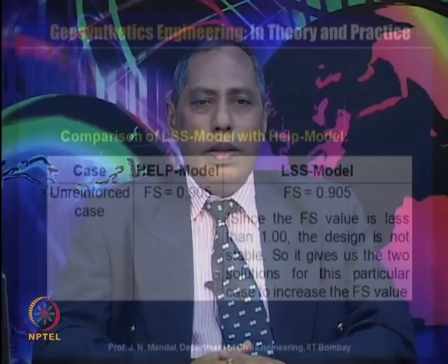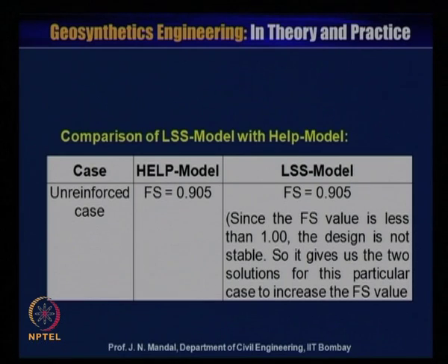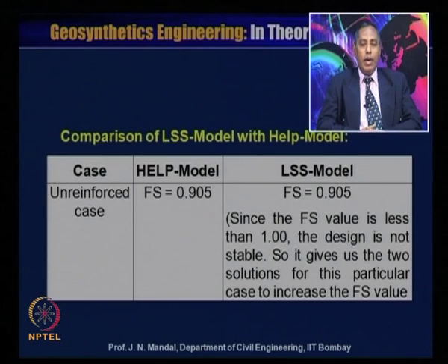Now, this is the comparison of the landfill slope stability model with the Helm model. For the unreinforced case, the Helm model factor of safety is 0.905 and the LSS model Fs is equal to 0.905. Since the factor of safety value is less than 1, the design is not stable.